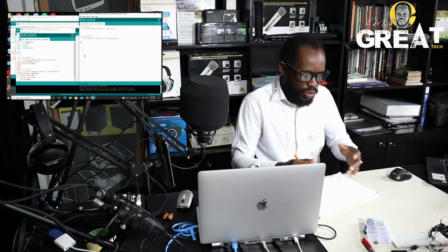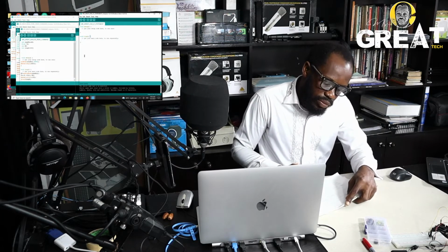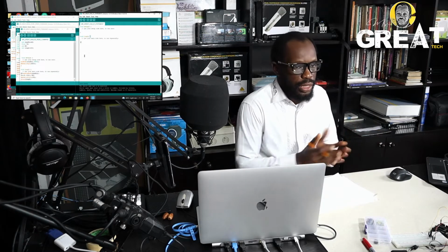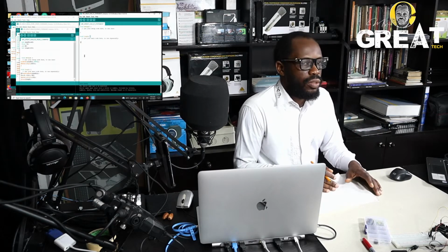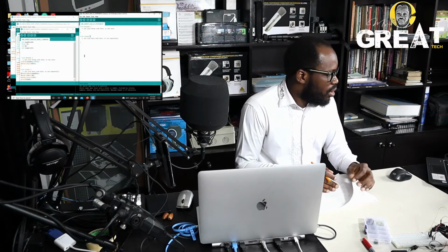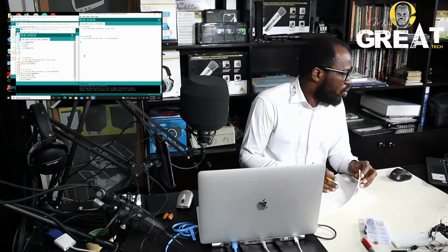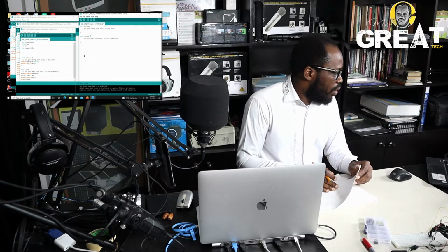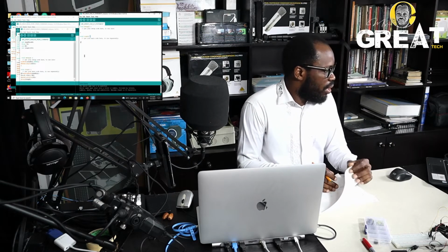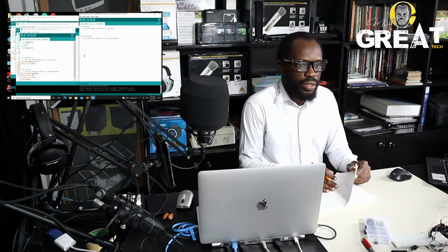So that is it. In Arduino, the if statement is what we use to make the Arduino act like a comparator. But in that if statement, which we are going to introduce in today's tutorial, we are going to print it out in the serial monitor. We have been printing in the serial monitor, and you can also call up your file if you still have that analogRead command where we read voltage from pin A5. We read it and we show it in the serial monitor.